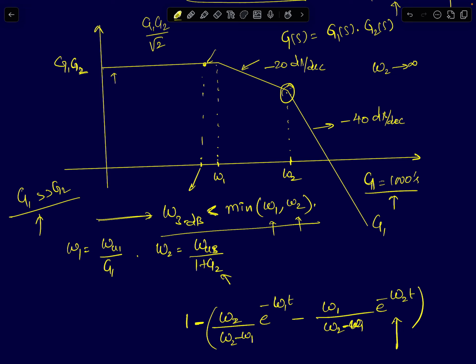I showed you some examples from data sheets. I showed you two instrumentation amplifiers, wherein in the first instrumentation amplifier, the entire gain of the amplifier was due to the first stage. Second stage gain was just unity. It was just acting like a subtractor, or a simple differential to single-ended converter with unity gain. So since most of the gain comes from the first stage, the first stage op-amp will dictate the frequency response of the overall instrumentation amplifier. That will dominate.